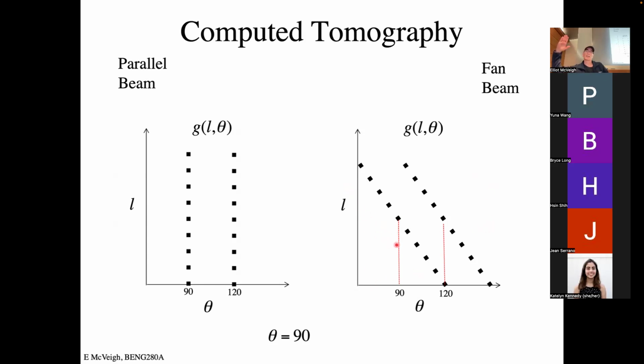And to do that, you have to scan more angles such that you keep going until this whole thing fills up. Okay, and so that means you have to do at least 180 degrees of rotation plus the fan angle. You've got to add the fan angle to fill in that gap.